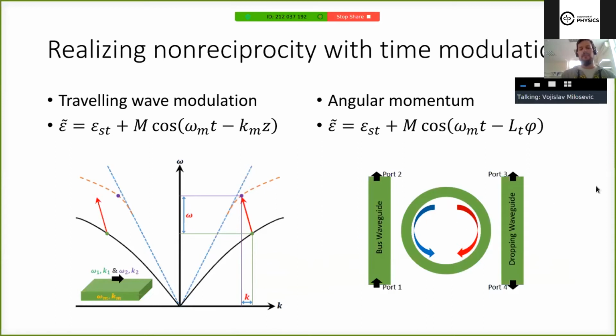again have sort of plane wave like modulation, but in circular form around this ring, and it will cause the lifting of the degeneracy of the two modes which exist on the ring. So it will produce different resonances for the different directions of the traveling wave along the circumference of the ring. So it allows us to create filters which have frequency difference for opposite propagations.